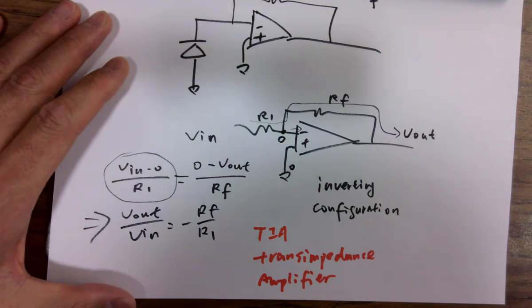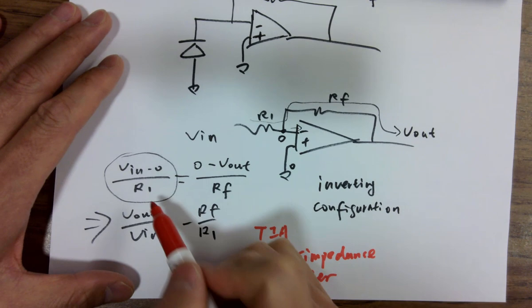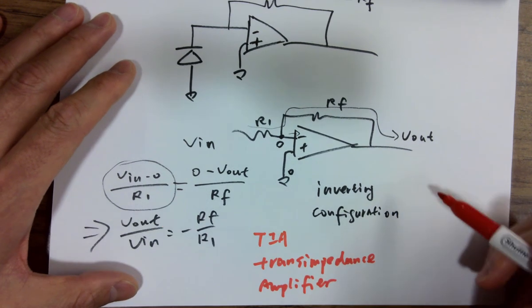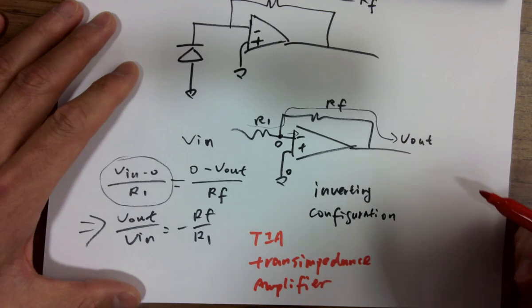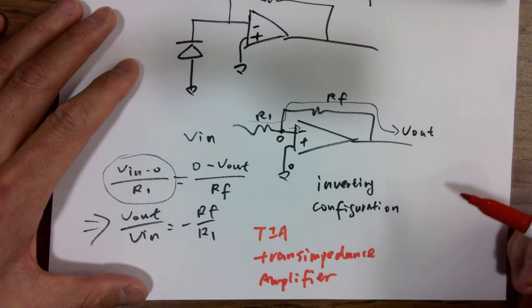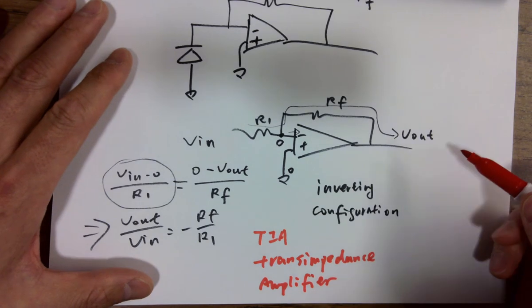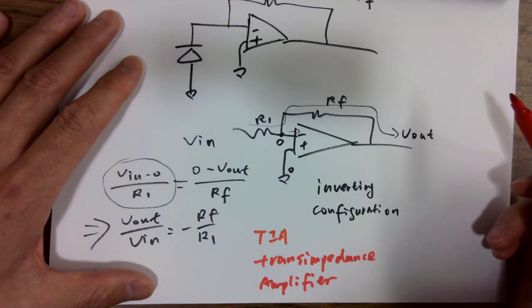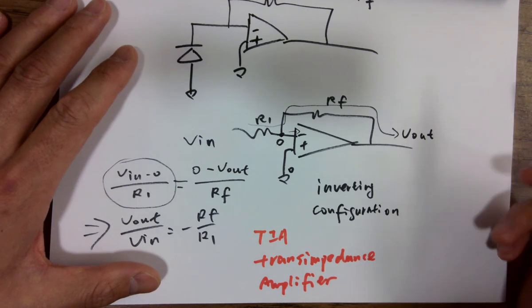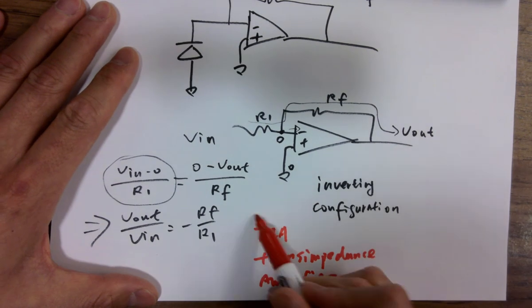Okay. So when you are deriving this voltage gain, you are using current. Did you notice that this is actually a current to voltage converter? Okay, very fundamental and basic point over here. But during the interview, you want to let whoever interviews you know that. If they ask you is it amplifying voltage or current, you should say, hey, this is actually amplifying a current. And this is called TIA.